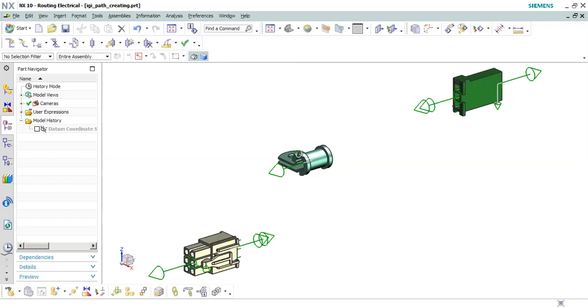Okay. A wire harness is a group of wires and cables that can be bundled together and are routed in various configurations to transfer electricity and information to and from various switches and devices. The designer builds a master part file for a family of harnesses. All of the lengths are determined with allowances for movement and interference. The master part file also keeps the harness to a minimum length.